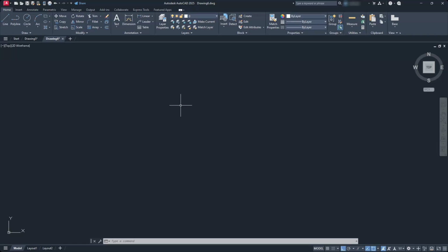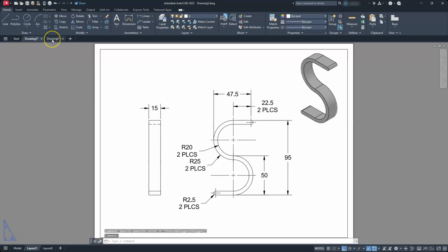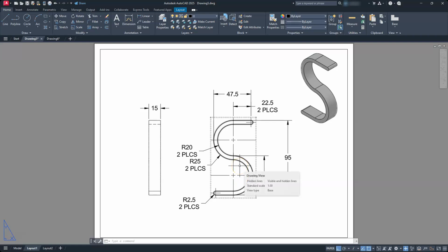Okay, so when I first look at this drawing, and I'm going to switch back and forth between here and my drawing here at the top, I see that I already know where the center is. I also see that these two centers are in line with each other here, right? So if I create a circle that has a radius of 20, and then a circle around it that has a radius of 25, I can create that. Now, if we want to do a little bit more math, here's one of those things: how far is it from here to here, right? I can either show you that, or I can let you figure that out, and it should be really simple.